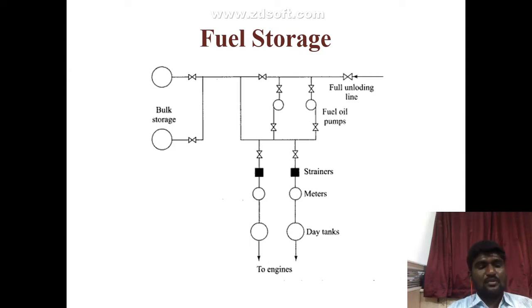What are the elements we should take care of while operating the fuel supply system? First, in all suction lines the pipeline joints should be made tight, with provisions for cleanliness and changing of filters during emergencies. The piping between the filter and the engine should be thoroughly flushed with oil, and all lines should be kept under pressure and the joints tested with soap solution, right?